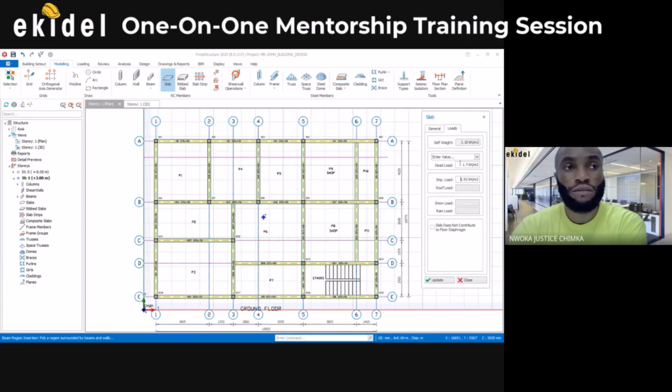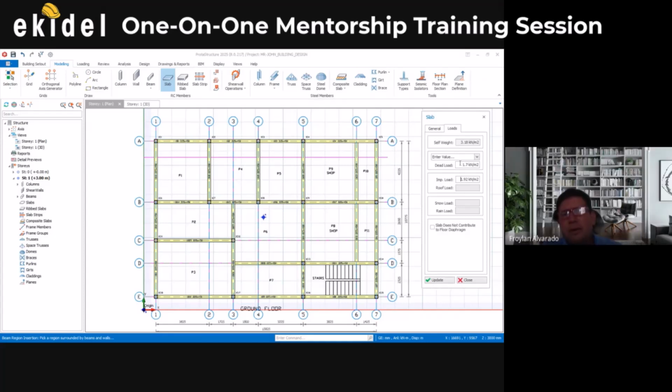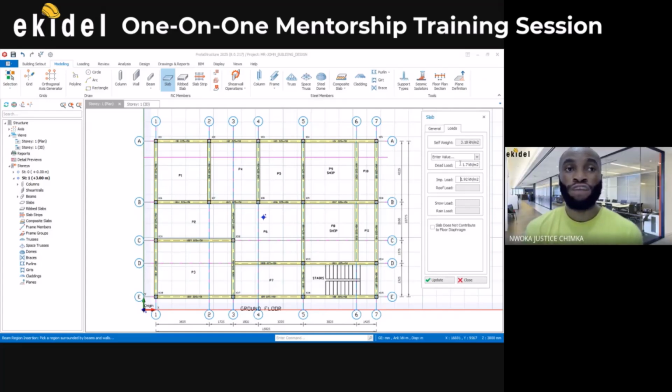But rain load is if you have a very high rain effect. There are some rains that when they're falling, what falls is ice blocks with it. Oh, okay, like hail. Yeah, hail. Those kinds of rains are very heavy, they come with blocks. So if your country experiences that, then you can add 1.2 as the rain load and all that. Although you cannot add it on the floor slab, it will be on the slabs that are being exposed.